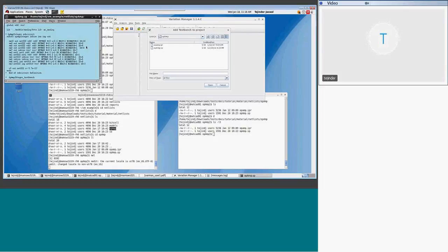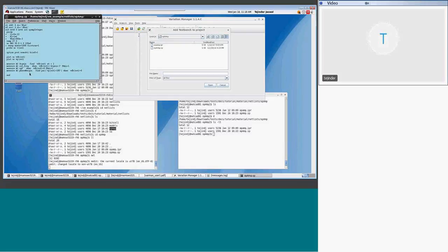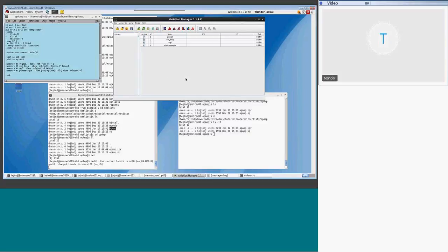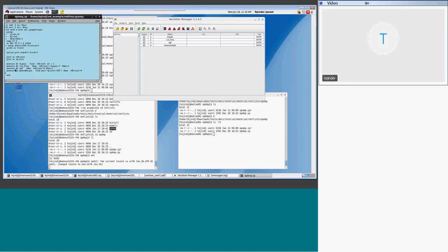Library models are here, and the netlist of the OPAM, and all the SPICE option files, parameters, and you can do plot, AC, and all the measure statements. So we say OK. Here we're going to pick that. I can go over the setup again. Basically, I'm just going to load this one while we talk. These are the parameters we define in this netlist, right? Here you can see DC gain, cutoff frequency, UGF, and phase noise. More parameters are going to show up here.